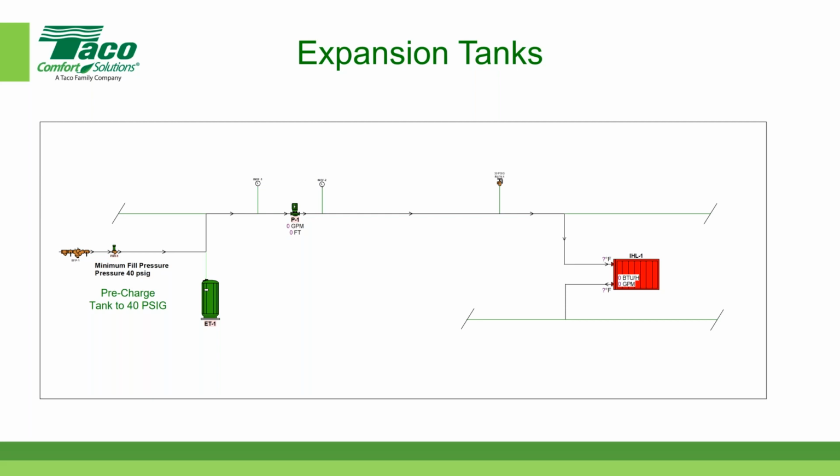And the reason you need to do that is that when you connect the expansion tank to the system, if the fill pressure is set at 40 pounds and the pre-charge was still at the factory setting of 12 pounds, then what would happen is that the 40 pounds of pressure in the system would start filling up the bladder and would not allow you the full expansion that you're looking for. So pre-charge is a very important concept.